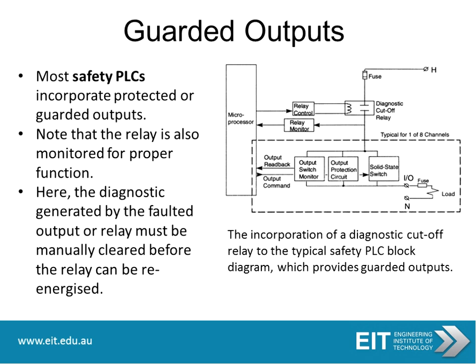Now again, going to the safety PLCs, they incorporate protected or guarded outputs. So previously we just had the dotted lines. So there's additional functionality which is now added. The relay is also monitored for proper function, and the diagnostics generated by the faulted output or relay must then be manually cleared before the relay can be re-energized.